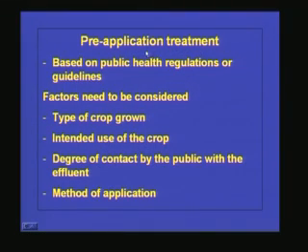And what pre-application treatment is required? It is based on the public health regulations or guidelines. So based upon the regulations, we have to achieve the treatment, and factors to be considered for this irrigation are the type of crop grown and intended use of the crop, degree of contact by the public with the effluent, and method of application. All these things are very, very important.